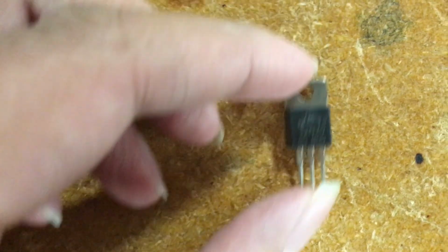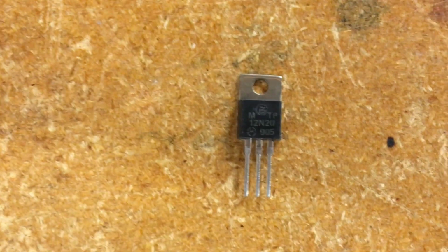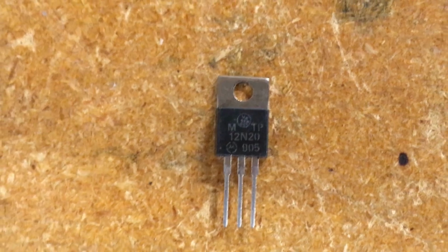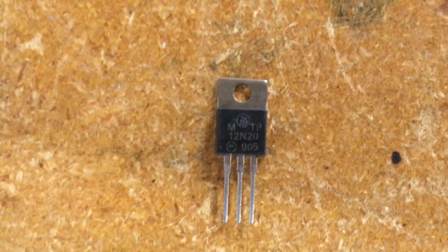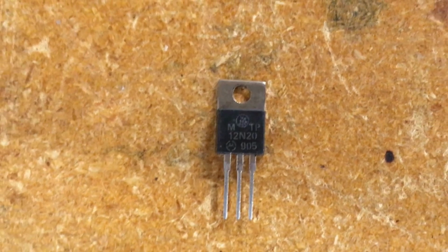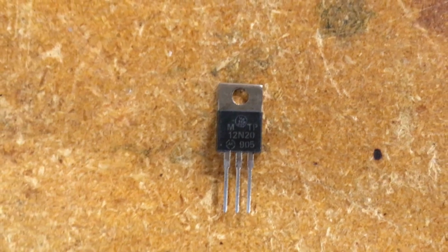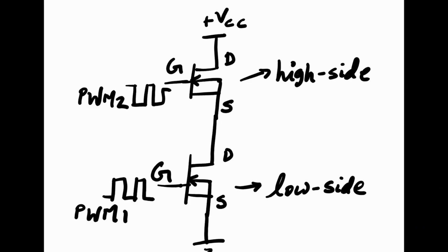Power MOSFETs and IGBTs are voltage controlled devices and require specific values of gate to source and gate to emitter voltage differentials to work as a switch. It is usually in the range of plus 15 volts to turn on and 0 or minus 5 volts to turn off. To drive what is usually called a low side power device, the setup is easy to implement since the source or the emitter terminal is referenced to the power supply ground.